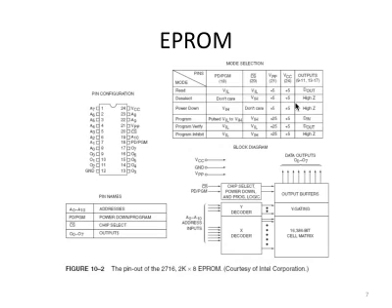And to program such chips, you usually need special tools or a special circuit to put this chip into programmable mode. And oftentimes you're going to have a different operation voltage applied to this chip, and also different control signals applied to put it into a writable mode, and you perform the initial write operation to write the initial data to this ROM chip.